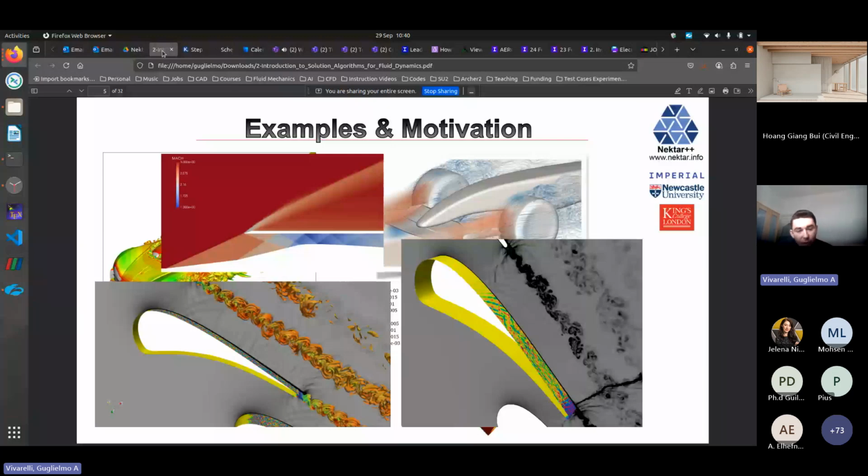And then, of course, as you ramp up the acceleration, how do you do that? Well, you just reduce the back pressure. A shock forms at the trailing edge, and you see that on the right-hand side. And just to give you an idea, this particular flow condition goes from an incompressible kind of setting at the inflow of Mach number 0.15, so you're well within the incompressible range, to 0.8 to 1.1 within 10 centimeters. So it is a rather expensive case to do.